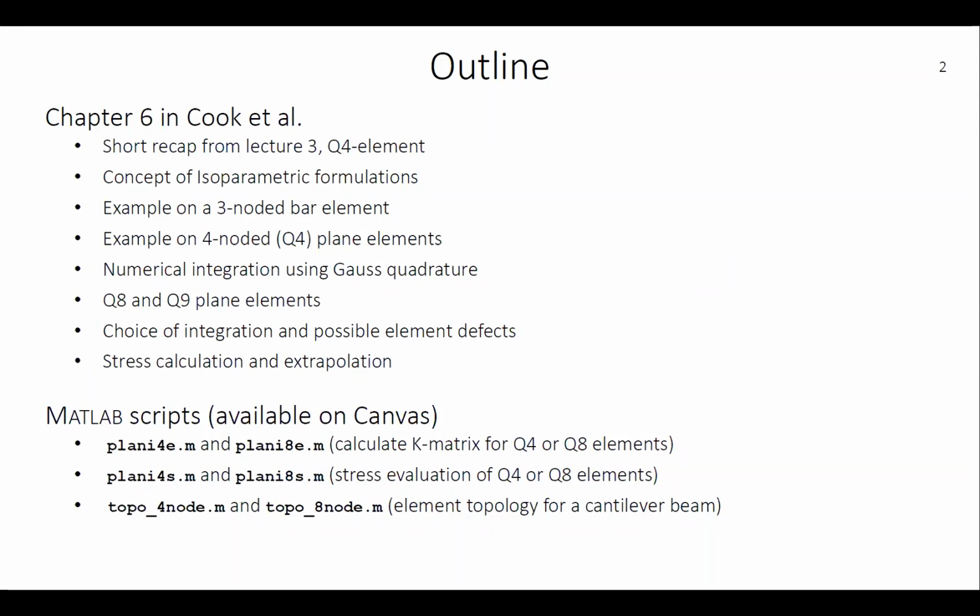Then we have two other MATLAB functions or scripts, Plani4s and Plani8s, which evaluate the stresses of these elements. So one is for assembling the matrices. Then you need to write your own code for assembling the structure and solving the system of equations. And then the other two are for post-processing to calculate the stresses based on the displacement field. I will show some template script for this in the end.